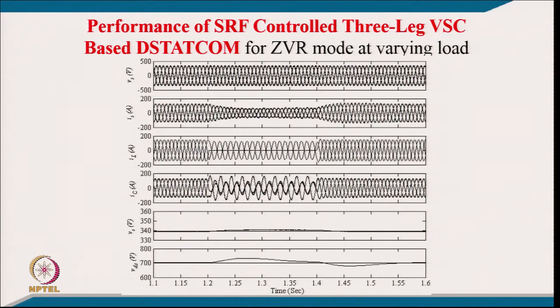You can just see it is the 3 phase PCC voltage, and the 3 phase grid current, which are balanced currents, but of course, they may not be in phase because you are using it for voltage regulation, maybe slightly leading. And this is the load current. You can see here we have a 3 phase lagging power factor load current, but here we have removed one phase in the 3 wire system. So, 2 currents, 1 return, it is like a single phase, one current is going and returning. So, this is load unbalancing to demonstrate,